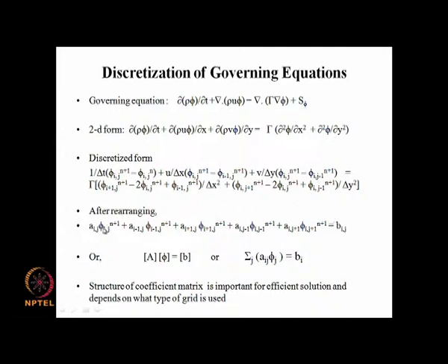This is our algebraic equation, and in the process we have linearized the u and we have accounted for the coupling with other equations in terms of v here. And for example, in the x momentum equation we have a source term which is not mentioned here, which is the pressure gradient term. So all those things are done and eventually we have an equation like this,